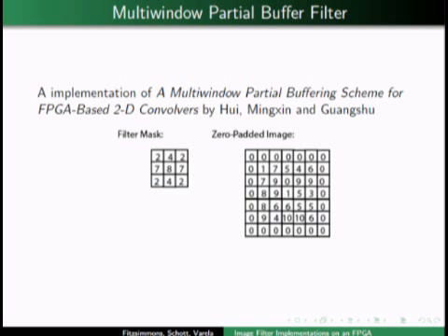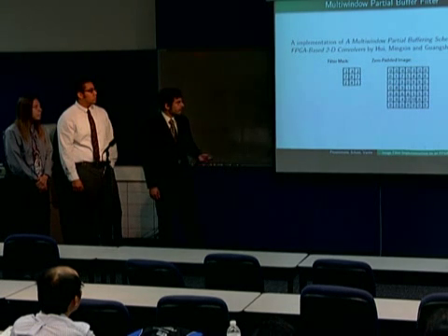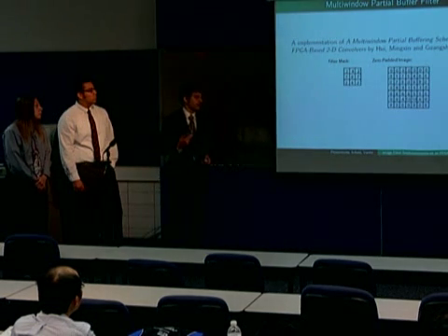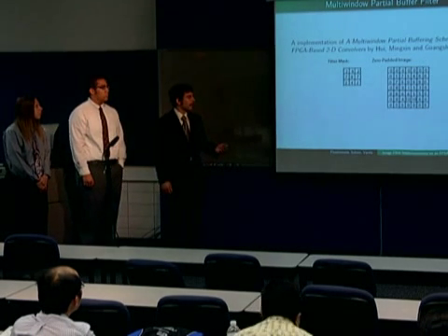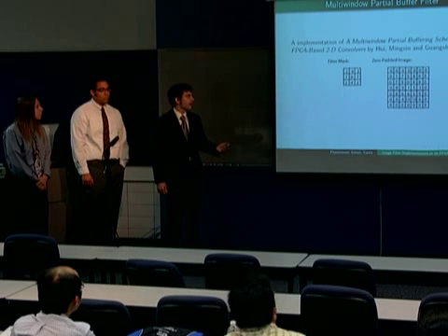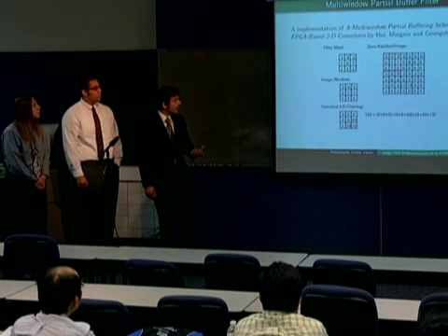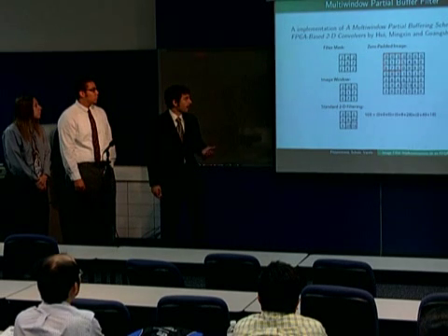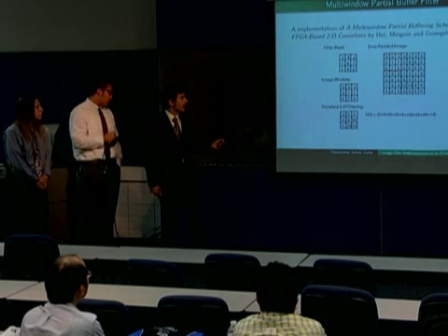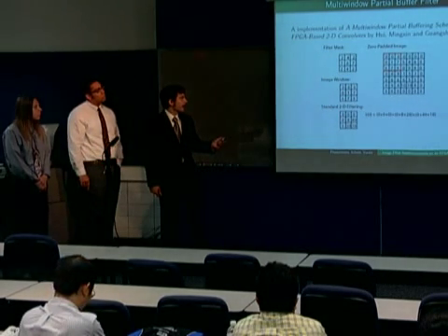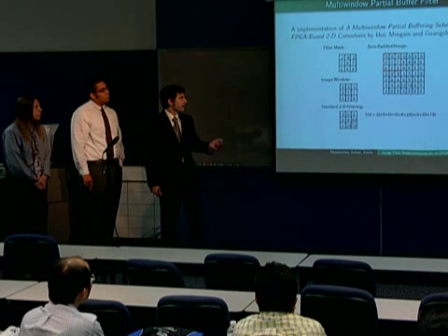So here we can see the filter mask we're using in this example and a zero padded image, which is the full zero pad in the horizontal and vertical directions, the x length or y length minus 1. So you can see we have 2 zeros horizontally and 2 zeros vertically with a 3x3 mask. And really this is just showing what convolution actually would be in 2D convolution. We have our window from the image, and then standard 2D filtering piecewise multiplies these together and adds them to yield the first pixel value of 103.